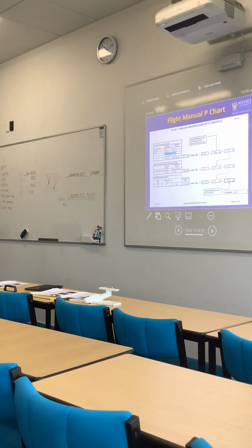So this is where we could do a short field takeoff. This graph itself does not calculate the distance for a short field takeoff. This is for a normal takeoff. So we can be confident that we could actually reduce this distance a little bit further by doing a short field takeoff. But our job is still not done. We've got to think about our own personal experience and personal confidence and minima.